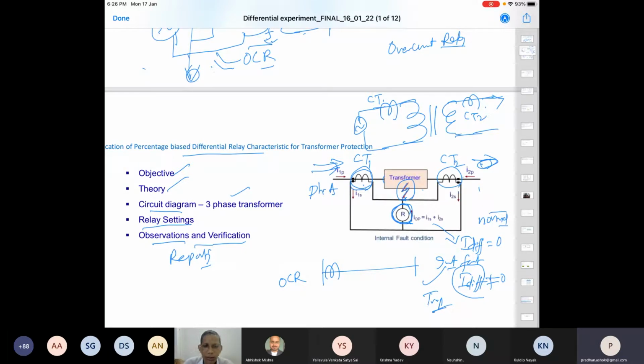So we started with overcurrent with one CT, which gives the corresponding current information only, whatever is through that path. Here, a fault happens to be there. This CT is able to give the input to the power current. And again, why do we require a CT? Because we have to downscale the current to a substantially low level so that it is compatible with your relay device. Relay is a fault detector. We talk about a numerical relay, so it is a numerical device. That current has to be converted to voltage, plus minus 5, plus minus 10, or whatever is compatible with the microprocessor, microcontroller, or whatever you are using.